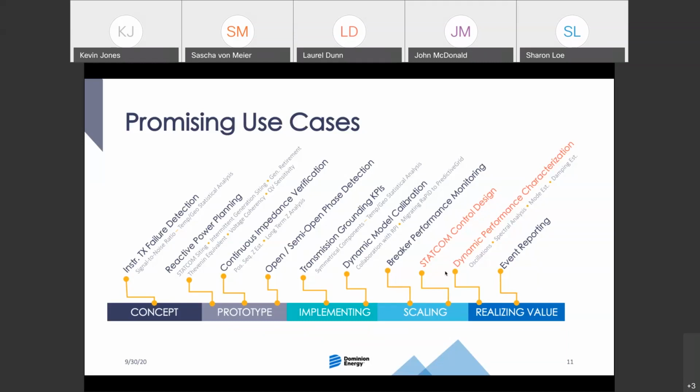And supporting both of those under the hood are really dynamic analyses of Synchrophasor data. If we recall the original question before the presentation about, can we use these things for more than steady state? So we're looking at oscillations. We're also looking at spectral analysis and mode and damping estimation. And as you'll see, we're not just looking at these in terms of discrete events on the system. We're looking at them in terms of the continuous and ambient data 24/7 across the system.